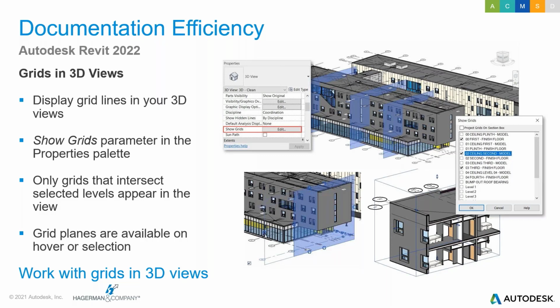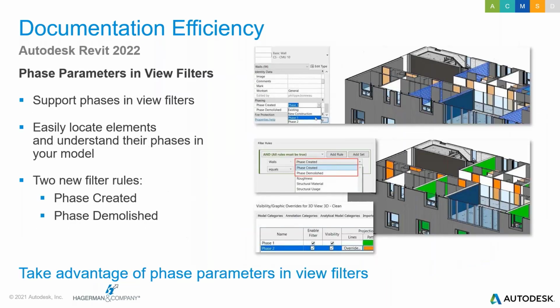If you want to hide part of your model, you can create a 3D section box. As you can see, the grid lines do not extend beyond the bounding box, making it easier to navigate this portion of your model. Small caveat here, I tested it and the bubbles will be outside of the section box, which I think is a good thing. So nice little enhancement there.